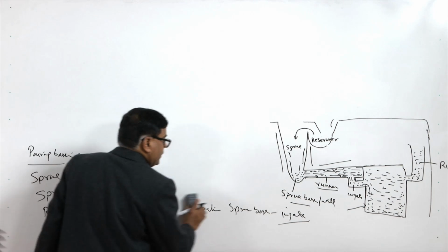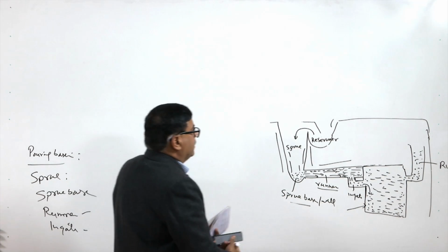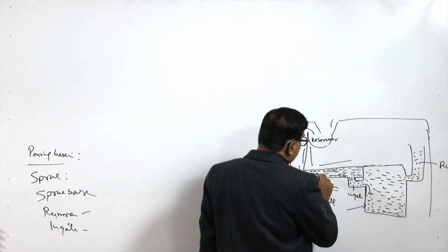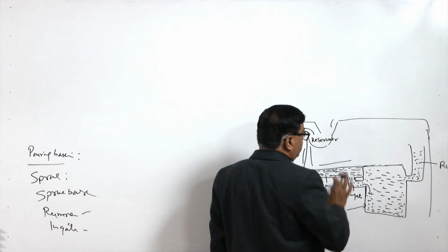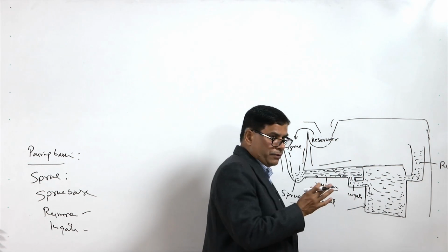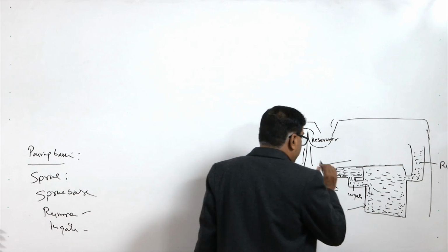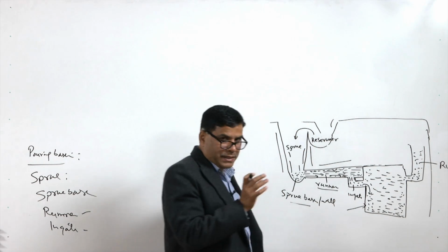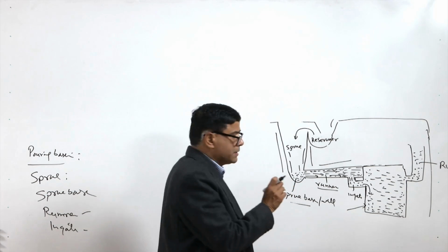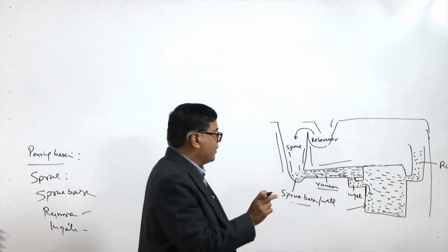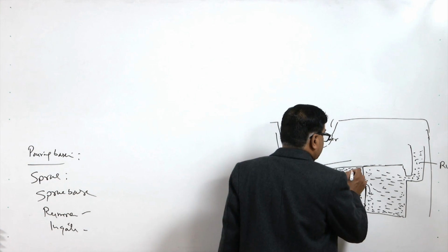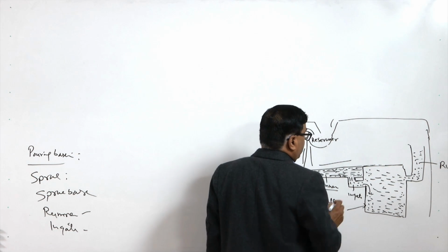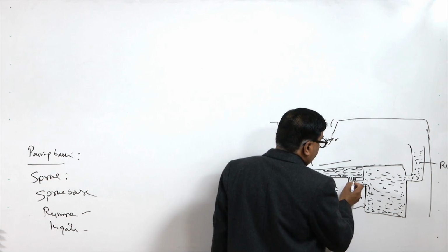Here, one typical feature is that it is always desired that the runner is always full of the molten metal, so that no negative pressure zone is created. But still, when it is full, the lighter, low density material like the impurities, slag, dross, sand, etc., will be floating over the top layer, while the molten metal is fed from the bottom.